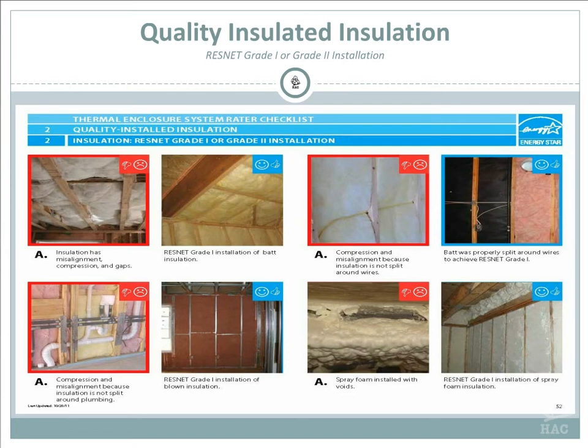Again, you look at the right one. The insulation's all over the place. It's crushed behind the wire. On the right side, the insulation has been split in half, so the wire is covered and runs through the insulation. It creates a smooth surface on the outside. Same thing down here. You can see all the different plumbing pipes. A lot of it isn't insulated. That whole area is compressed. The insulation is compressed. They just kind of stuffed it in there.